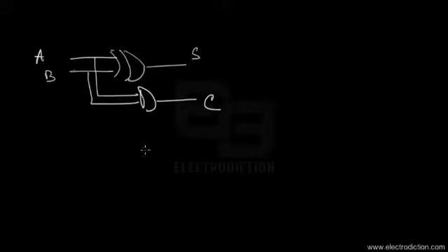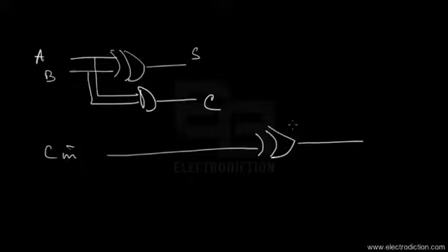And here is the carry bit produced from the half adder as well. So there goes our carry. This is our first half adder, with input bits A and B, and here's our carry in bit feeding straight into the XOR gate of the next half adder 2.